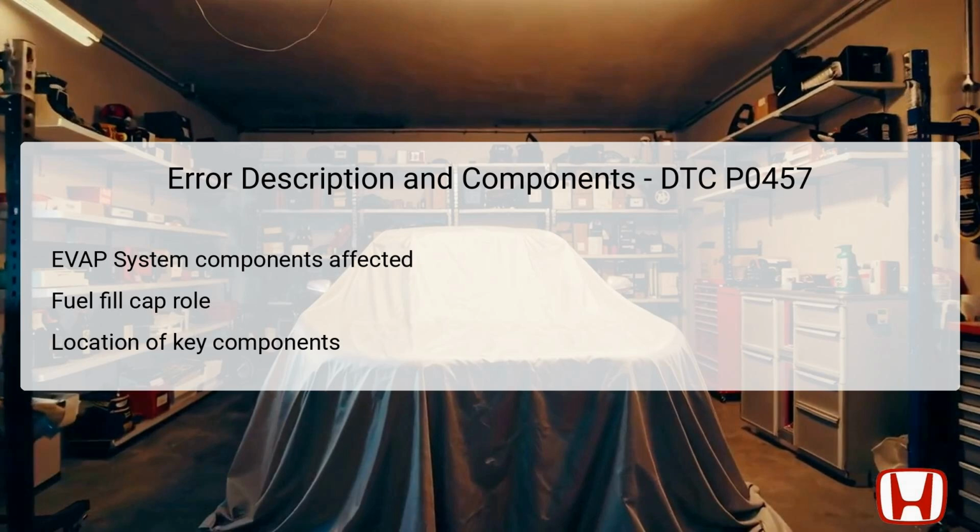It's typically located on the rear side of the vehicle, in or near the fuel filler neck. Additionally, the system comprises the EVAP canister vent shut valve, which controls the flow of fuel vapors when the engine is running versus when it is off. Failure of any of these components, especially the fuel fill cap, can cause the system to detect a leak.